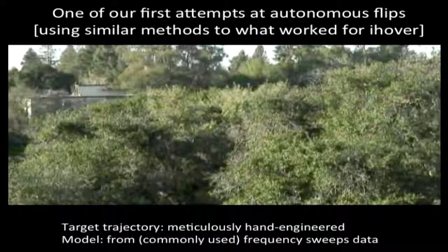So what happened here? Physically, what happened is that the controller pushed the controls too hard. As a consequence, the engine could not keep pushing the blades around. There was too much air resistance, and the engine just died. The moment the engine died, you lose control over your helicopter to some extent, not fully.